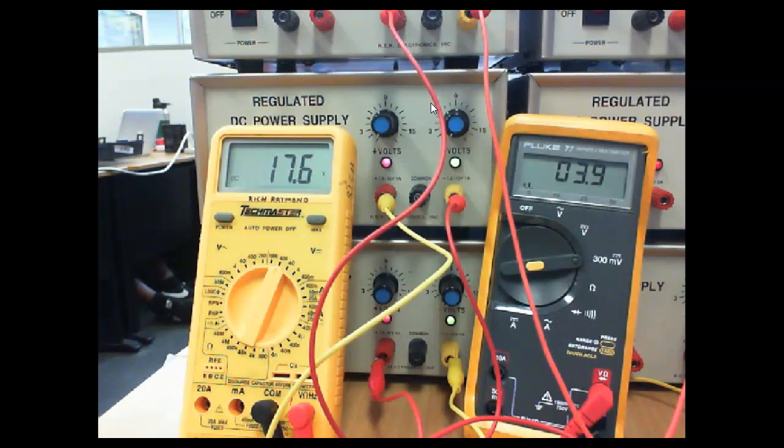So this is one of the reasons, if you let the leakage current get out of whack, you're going to cause problems. Because this thing's dropping a lot of voltage, and anytime you have current and you have voltage, you have watts, right? You understand that? So this is what usually damages it.